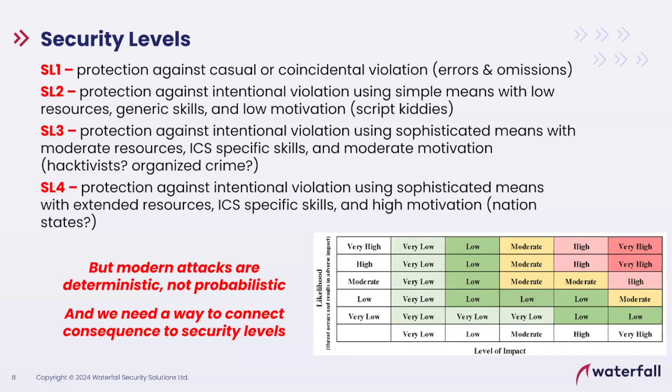And a second failure, if you apply routine safety thinking to cyber, is that in the safety world, these random failures are independent. If one safety component fails, it's no more likely than before that other safety components will fail anytime soon. Whereas with a cyber attack, you've got deliberate threat actors going out there, and if they can figure out how to take down one of our safety systems, they will apply that same attack to all four redundant safety systems and take them all down. If one goes down, it's very likely that other similar systems are also going to go down.